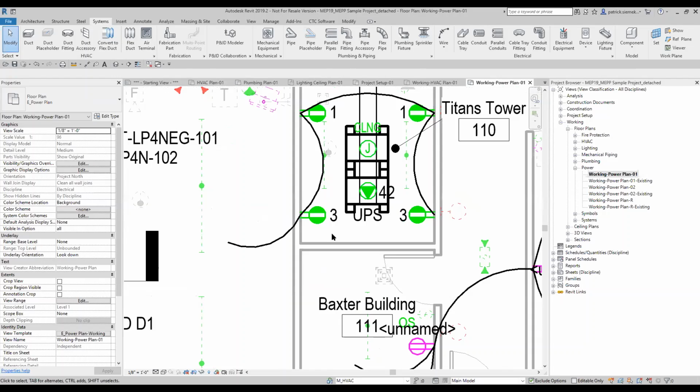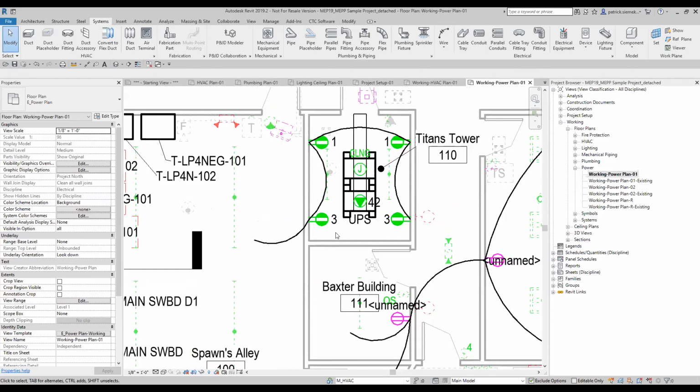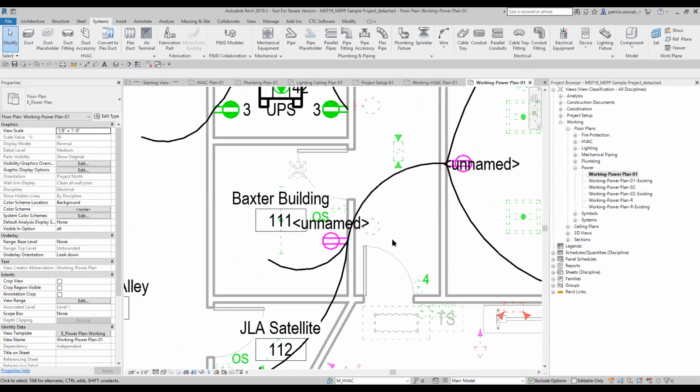Your green items within the electrical side, if they are green, that means they have been created as part of a system. They've been circuited along with being assigned to a panel. So that's where we have the green indication. Your magenta colors are elements that have been circuited but not applied to a panel itself. So again, another indication of what has actually been done within that item.